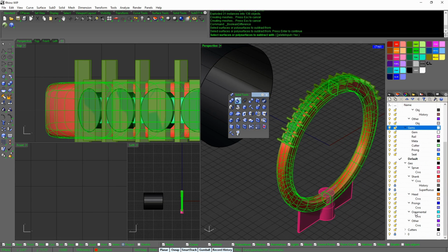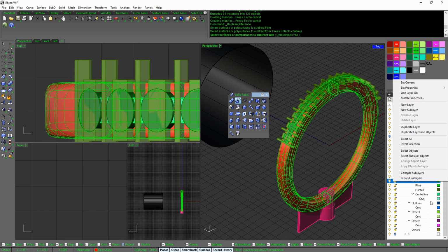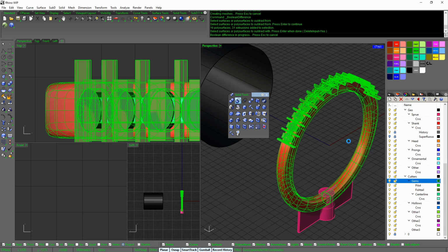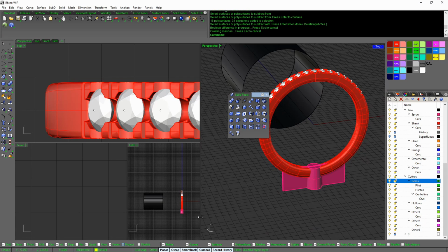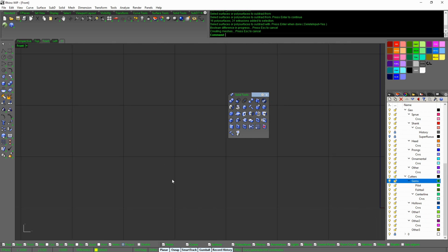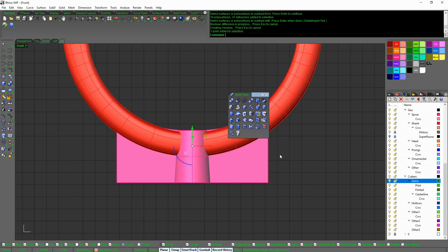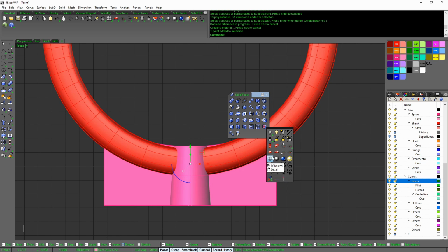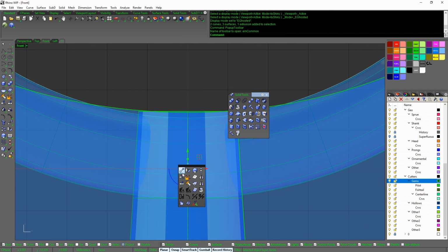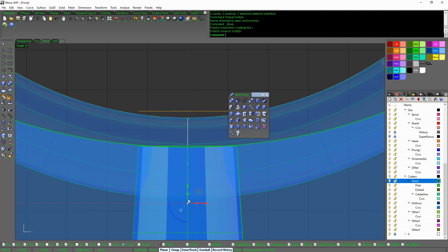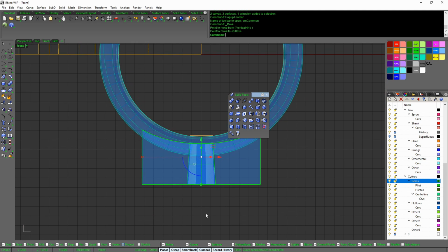and select everything under our gem cutters. Select sublayer objects. All the booleans are done. There's the gems. Our center sprue. If we look at it with the right mode, we want to move it from this point down to here, and then we've got a 3mm sprue.